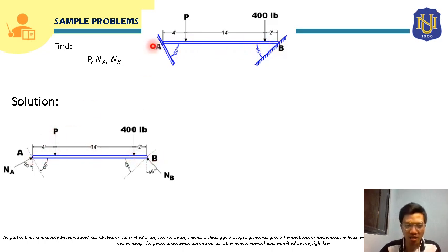So here at A, this is supported by this incline. This surface will provide a normal reaction, and its point of application will be at the point of contact of the bar and this surface, so somewhere here. And this normal force will be applied 90 degrees, or perpendicular, to this surface, so it will be applied this way.